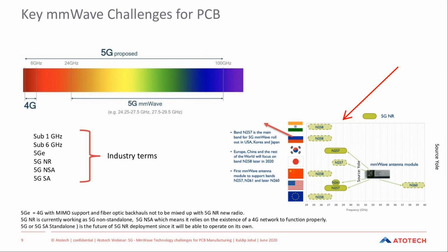And what we can say is that typically that bandwidth is going to be anywhere from 24 gigahertz all the way up to about 30 gigahertz. And that's going to be the main frequency where 5G is going to be used. So as we move to 5G, we're also going to see the use of massive MIMO and beamforming to ensure that we can get line of sight to make millimeter wave work, given that millimeter wave propagation distance is much shorter than obviously the other spectrum radio waves that we would typically use.